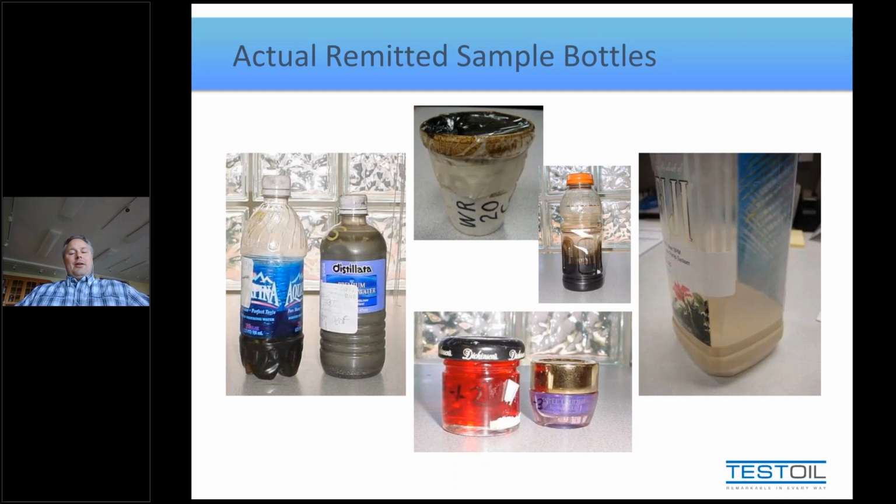But if you keep going around the clock there to the 3 o'clock position, you should see a Fuji water bottle. Now, if you look at the oil, can you tell what's wrong with the oil? It kind of looks like there's water in it. So now this begs the question, is there water in the oil, or was it just water in the bottle and it's not mixed in the oil? So it's misleading things like this. The contaminated or reused sample bottles are just going to constantly prompt questions but aren't really what you're trying to find out.